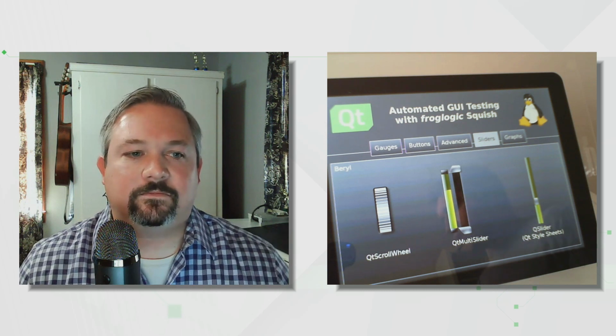Okay. Where do the names come from? Is the names.py written automatically? Yes. Whenever you record with any of the controls or you verify any of the controls, the proper entry is added to this object map, to this names.py. And this file can be shared among all test cases and all test suites. It can be a global one, so there is no need to have duplicate entries among multiple test cases.